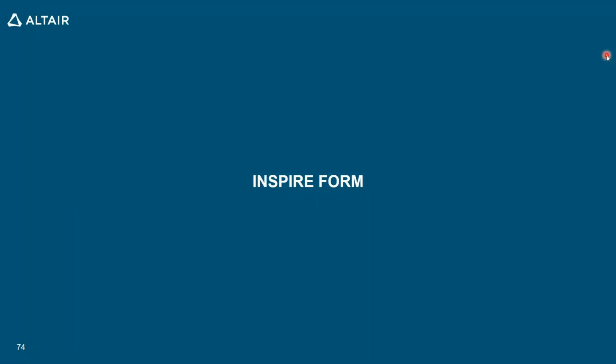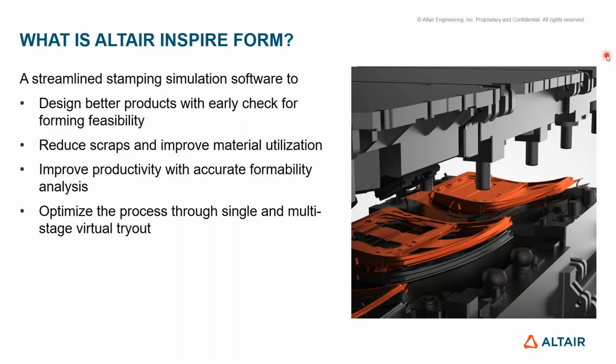And coming to Inspire Form, Inspire Form is the sheet metal forming simulation tool where you can perform different types of sheet metal forming simulations, such as one step forming as well as incremental analysis. You will be able to get the formability limit diagram where you can determine the wrinkles and strain region, thinning, thickening, and so on.